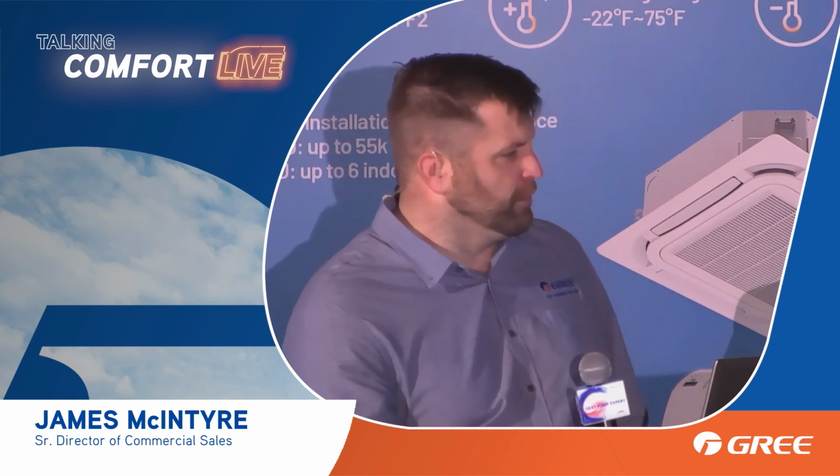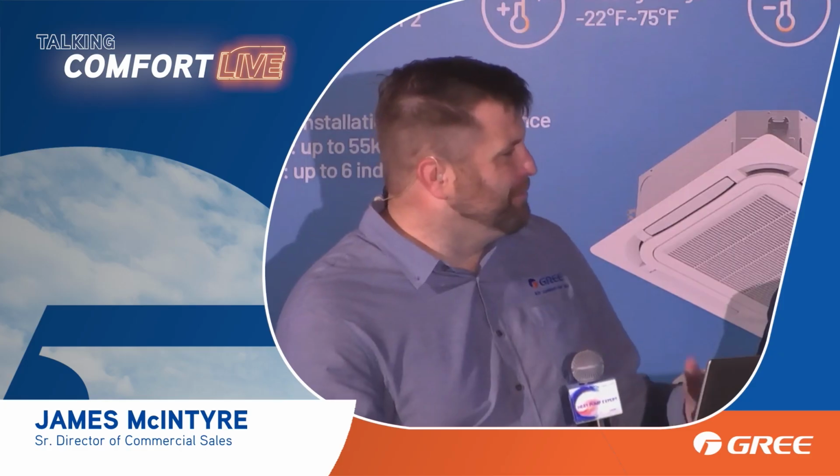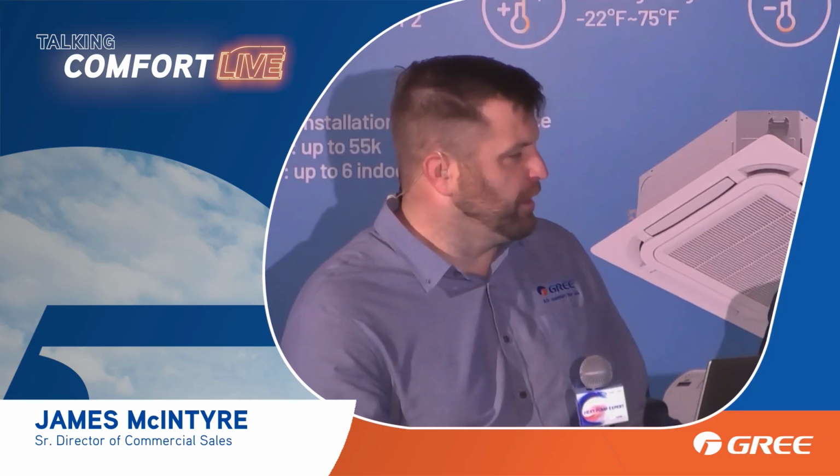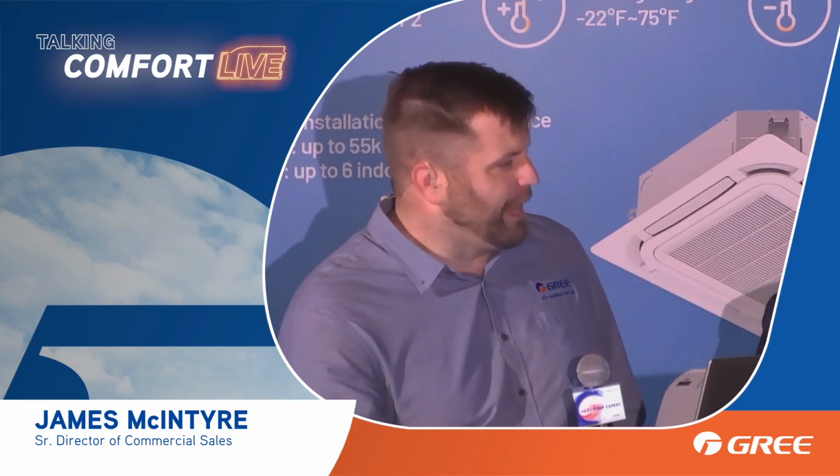I mean, we are able to use less refrigerant, for example. Looking at the BTU output, I would have to have a lot more R410A to get the same result, so I'm using a lot less A2L refrigerant right out of the gate. That's one of the advantages. In addition, higher discharge temperatures: we use that to our advantage since we use high discharge temperatures to get you heat at minus 22. It may not be an advantage for somebody who doesn't use inverter-driven compressors or try to do ultra heat, like regular standard stuff. They may have to lower their capacities a little bit, but we can use that to our advantage. And then finally, the efficiency ratios are naturally higher.